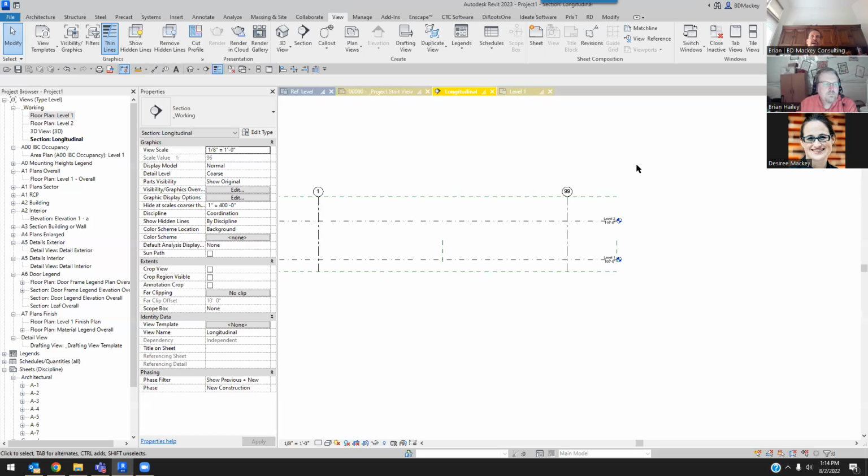And their tag then tagged the rough opening that they frame it to, so then their guys on the site could do it. So they'd put these openings in, not only tag how many trimmer studs, king studs, et cetera, but they would then go in and tag everything in the one tag. It was not actually structural framing members because they didn't care. They didn't need it. But yeah, it was actually very cool when they got into it.